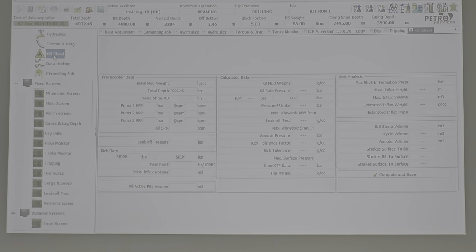But first, before, you have to record daily the SCR, slow circulation rate, which the rig makes every day at midnight, between changing the handover, the shifts. They make something called pump circulation rate. SCR, you know SCR? Slow circulation rate.